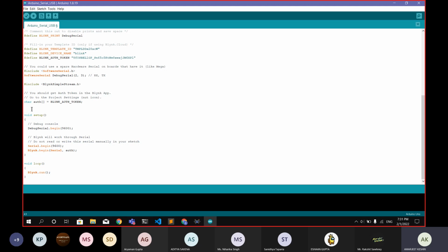So before moving on, remember we have created the virtual pins, the data streams. How do we use them to write a digital quantity or an analog quantity? You use this function, Blynk write.